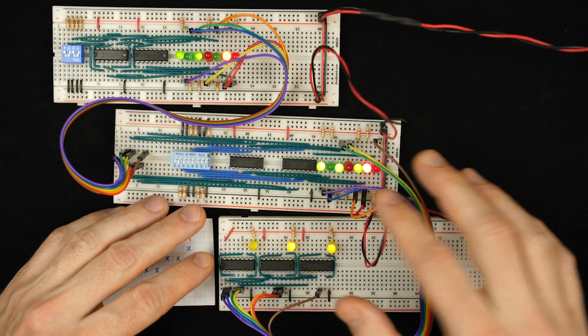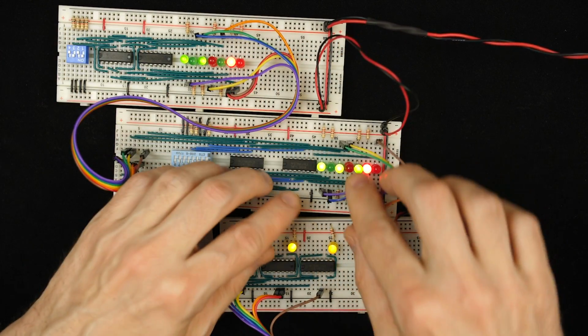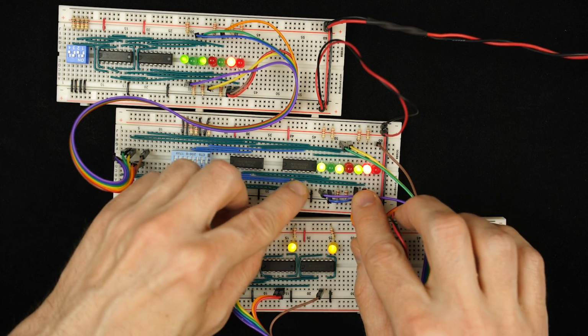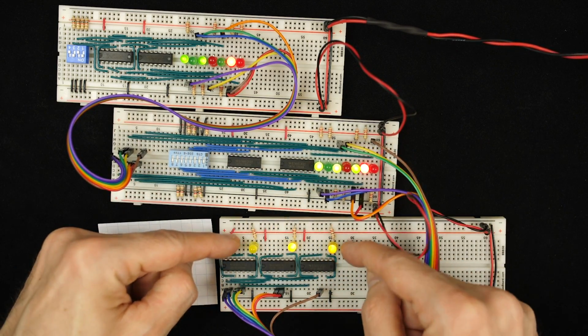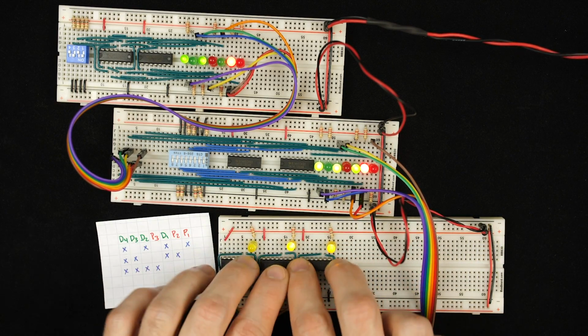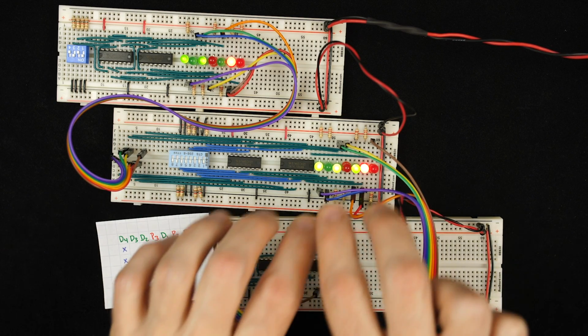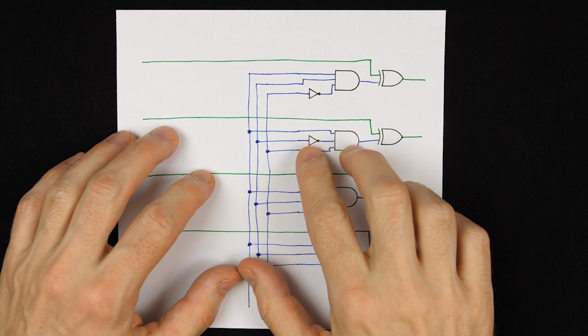But anyway, now that we are able to figure out that bit 3 is wrong, the next thing you want to do is, if we're using this in some circuit, presumably if we stored this particular data, 1, 0, 1, 0, we want to be able to read 1, 0, 1, 0 from somewhere. So we've got this data with an error in it, and we know where the error is. The next thing we want to do is build a circuit that takes the information about where the error is and uses it to actually correct the error. So how do we do that? How do we use that 3-bit binary position of which bit has the error to flip that bit back to the correct value? Well, we can use a circuit like this.